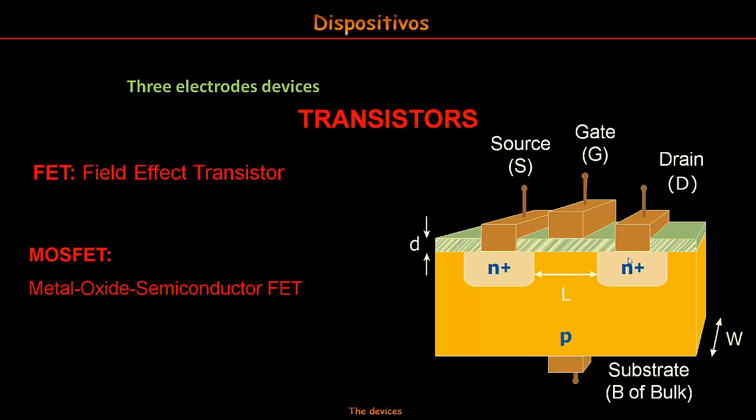A silicon oxide is grown on the transistor except in the points where the contacts to the electrodes are going to be made. Electrons can cross from source to drain, and the voltage applied to the gate can control the width of the channel formed between these two zones. Again, the transistor effect appears in that way.